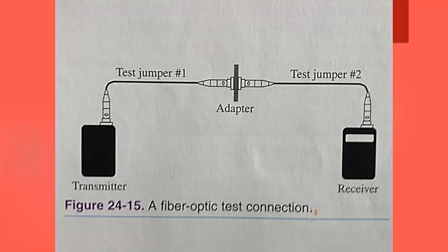Figure 24-16 is a sketch of a readout of a sample fiber optic system. The display of the cable system on the screen is known as a signature trace. In the illustration, an entire run of cable including splices and connectors are displayed on the screen. The sloping line is the indication of the attenuation of a section of optical fiber. The vertical spikes indicate reflective events caused by splices or connections.